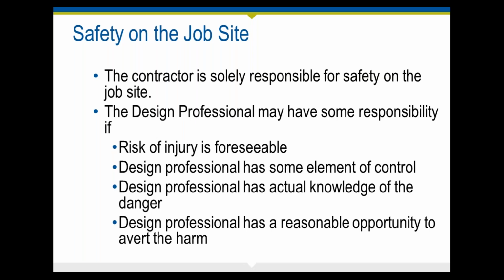So as we said, the contractor is generally solely responsible for safety on the job site. And really, the reason for this is the control element that I mentioned earlier. When construction begins, the owner formally relinquishes control over the site, and it is the contractor's responsibility to secure the site, control the access points, and maintain it in a safe manner. That is why it generally doesn't make sense for a design firm to assume any kind of responsibility for safety on a job site, because simply you do not have any control over the construction site, nor do you have any control over the personnel that may be working on the job site. So without control, it really does not make sense to have any kind of responsibility for safety.